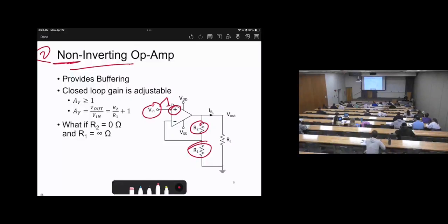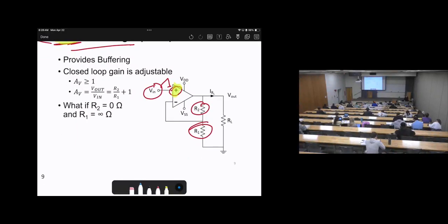Then this is called non-inverting. What's the point of calling it non-inverting? It's on purpose, because the input enters the positive. If the input enters the negative, it will be called an inverting amplifier. Then, how will the formula be? V out equals the closed loop gain times Vin.